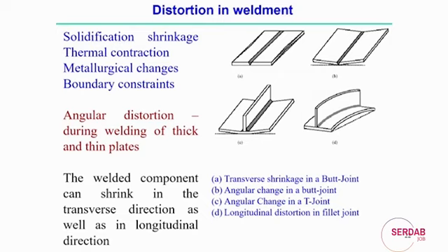So, depending upon whether the distortion is of a concave type, a convex type, or simply angular distortion, all can be measured straightforwardly, probably using a simple coordinate measuring machine or some laser scanning system, with respect to some reference point.